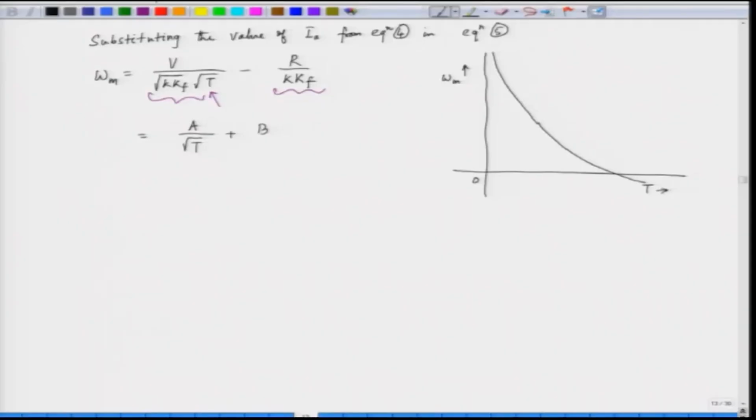How do you vary the speed? Let us talk about the speed control. Same thing here, we can control the armature voltage and the armature resistance. So, we first talk about the armature resistance control. Let us write down this equation once again.